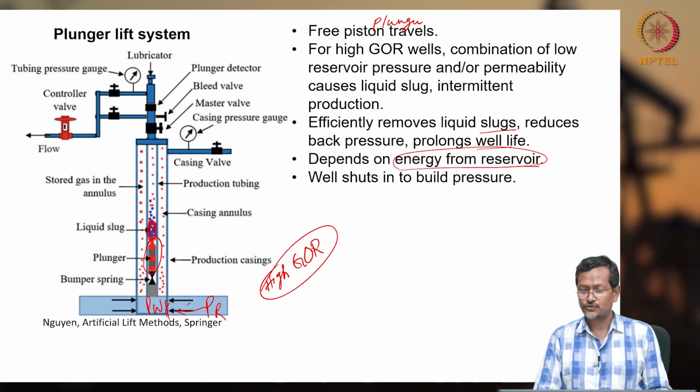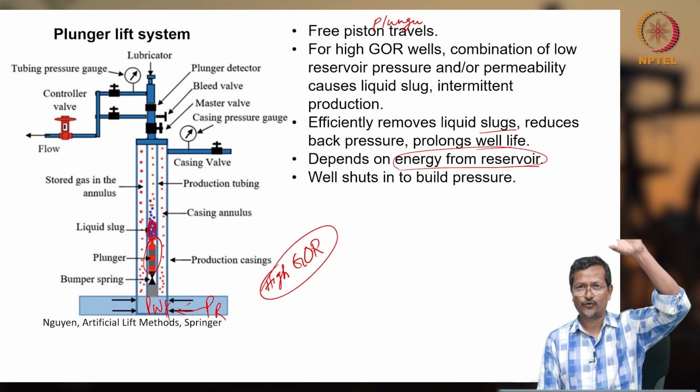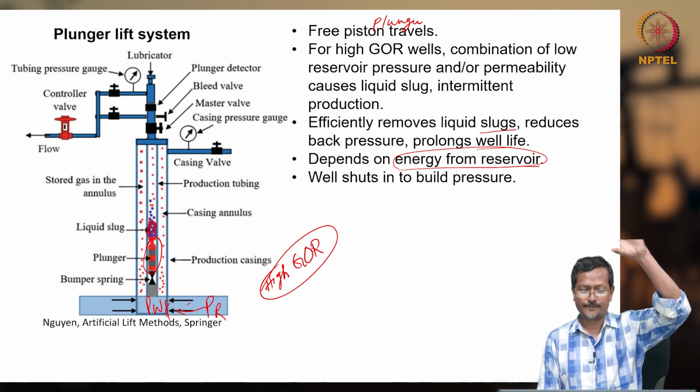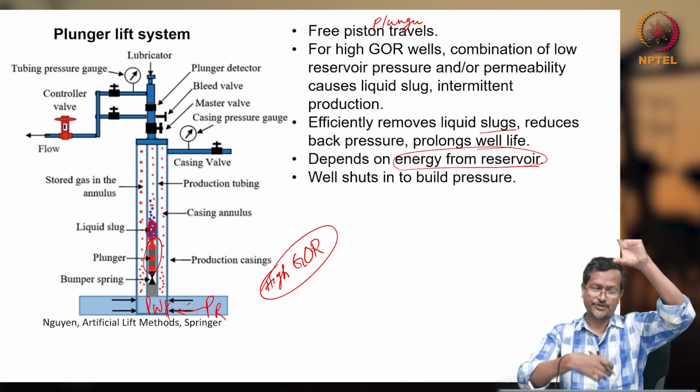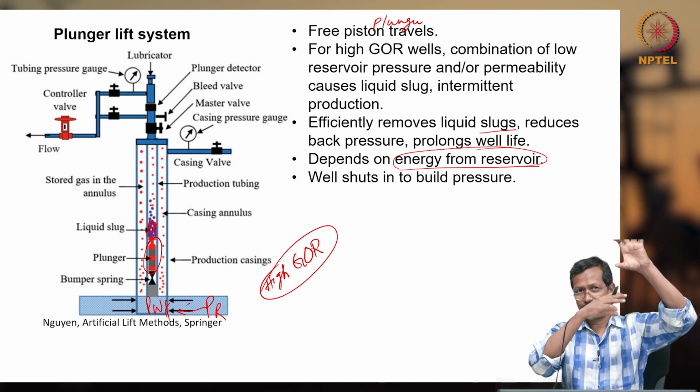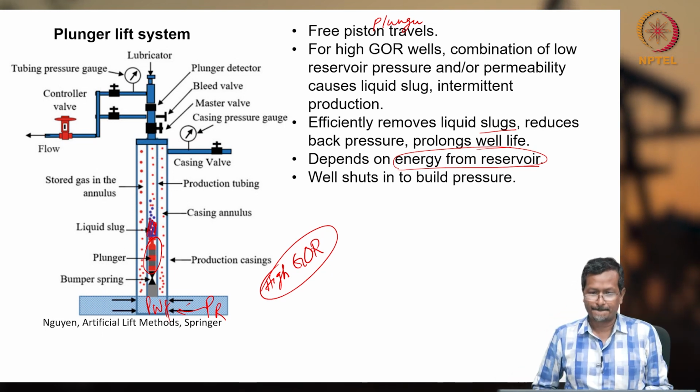Well shut-ins to build pressure. Okay. When the plunger is on the top, held by the lubricator, at that time you have to shut in, so that enough pressure will be building up, again you release it, again you leave it, so the system will continue.